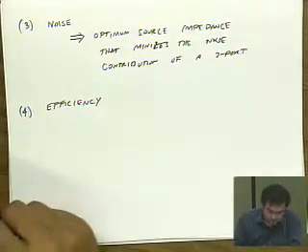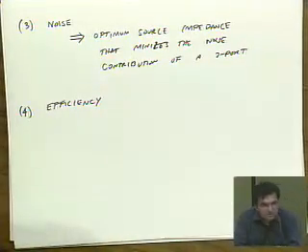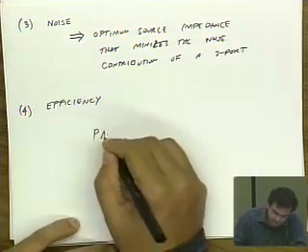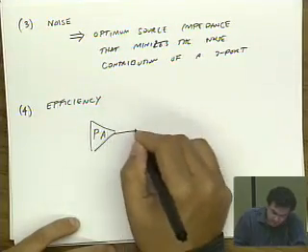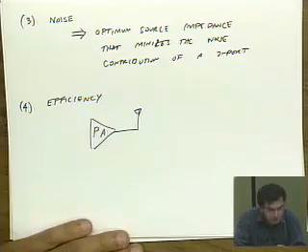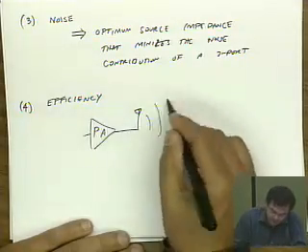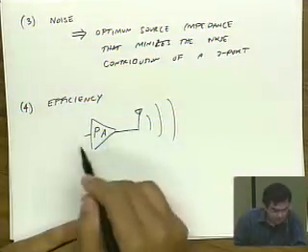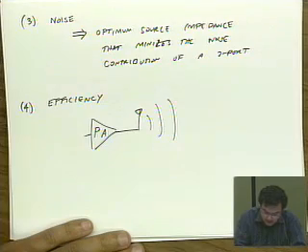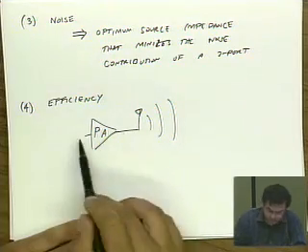It turns out that a lot of times power gain is not so important as power efficiency. A good example of that is a power amplifier, let's say sitting in your pocket transmitting data on your cell phone. Turns out that this power amplifier is probably the dominant power consumer in, let's say, a mobile communication device. And you might be able to give up power gain.